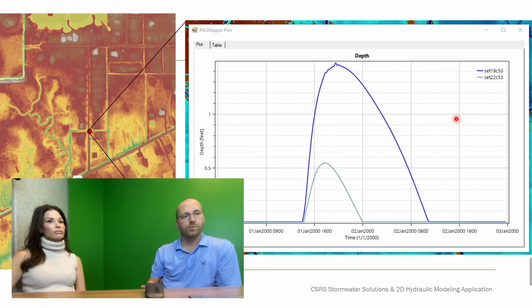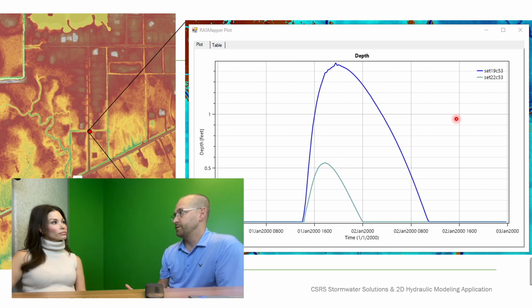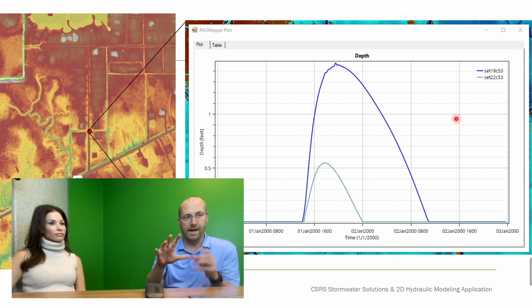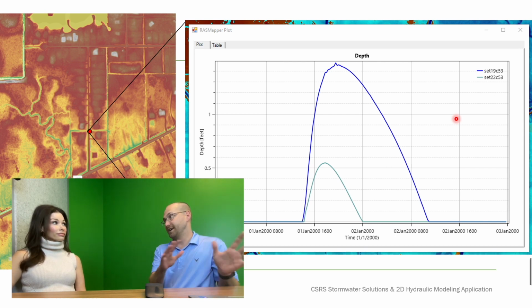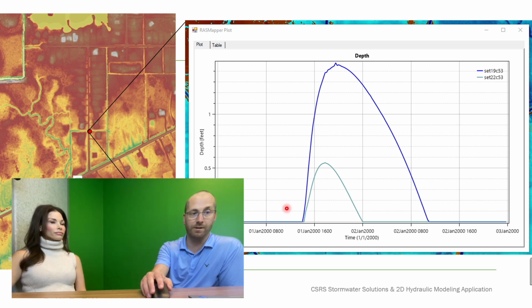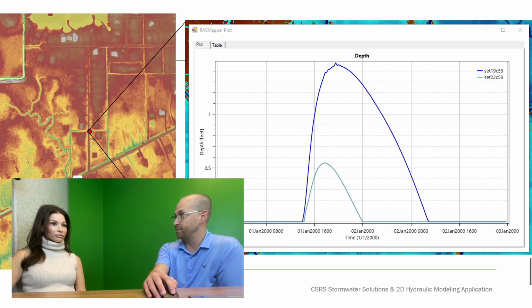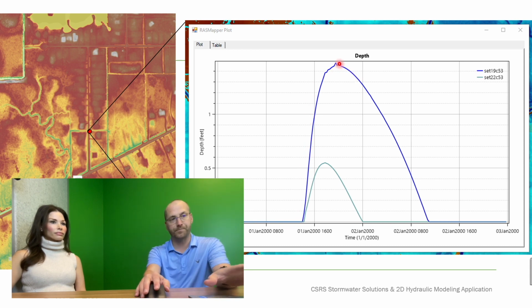That's another communication piece of how we can quantify the benefits from proposing these projects. I also want to talk about another piece of information we can get from these models. It's not as flashy or as easy to understand as an aerial image looking at flood depths. So we're back to some of the traditional communication of flood risk, where you're looking at a hydrograph. This is understanding the depth of water on top of the roadway at this point through time. So it rained, the water's flooding, the water's now on top of the road, and this royal blue line is existing conditions in the 25-year storm.